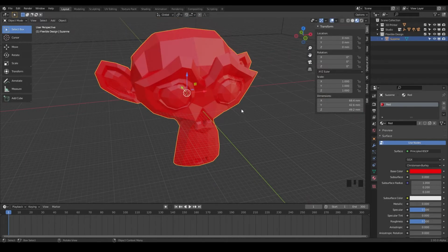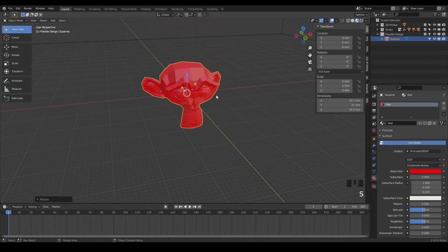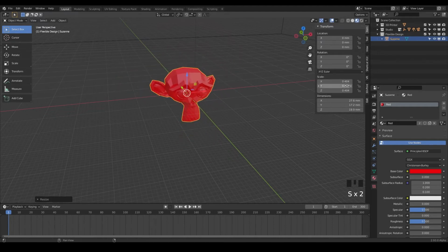One thing you will hear a lot about scale inside of Blender is that you always want to keep your scale ratio at 1. Say you've scaled your monkey down just here. Notice that since we scaled it down, the ratio went from 1 to less than 1. This can do a lot of weird things when we start adding effects to our designs. Say we wanted something to be 1 millimeter, it wouldn't actually read correctly because our scale would be messed up. So in Blender, there's an easy way to fix that.